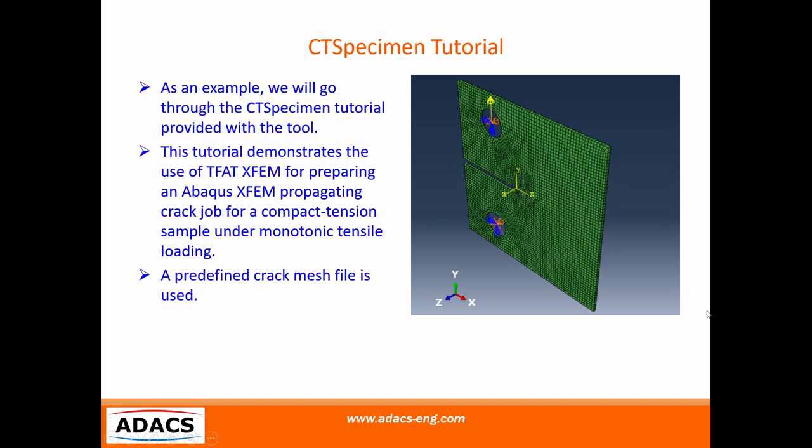As an example, we will run the CTSpecimen tutorial provided with the tool. This tutorial demonstrates the use of TFAT XFEM for preparing an Abaqus XFEM propagating crack job for a compact tension sample under monotonic tensile loading. In this tutorial, we will use a predefined crack mesh file.